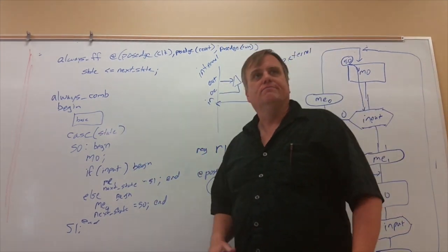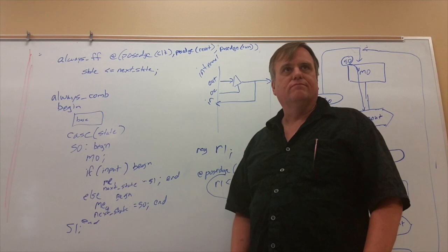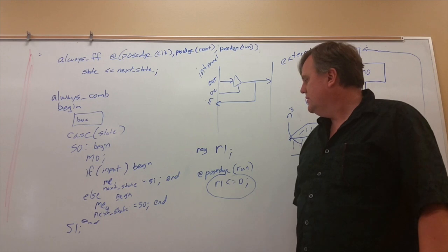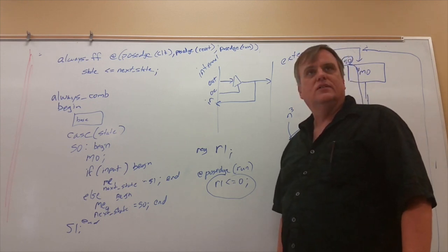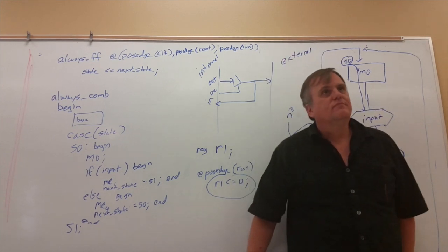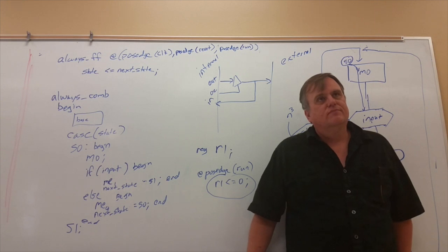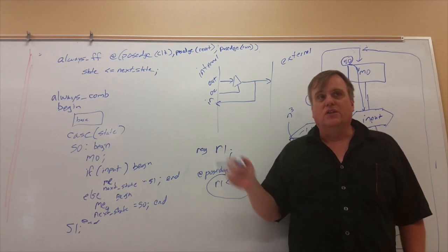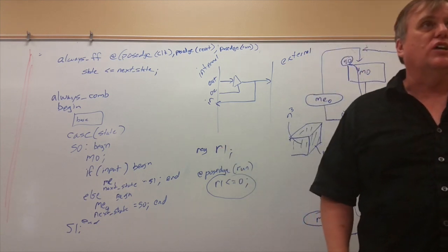I understand. Let's say we have a 4-bit shift register. I could use that kind of initialization statement to initialize the shift register as any type of bit pattern I want, like 1010. Once the clock enable is enabled, it shifts 1 bit from input and outputs 1 bit from the top bit. So what kind of circuits is this initialization statement synthesized to? If I put the equal 0, there's no guarantee it can, and it probably won't synthesize anything.